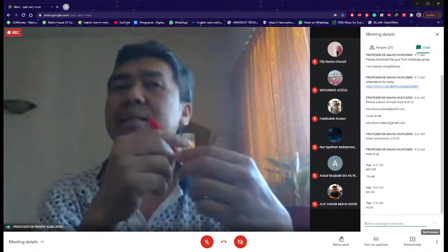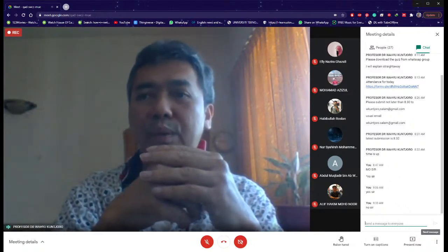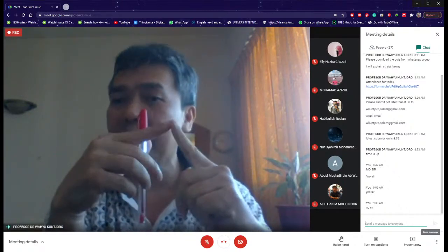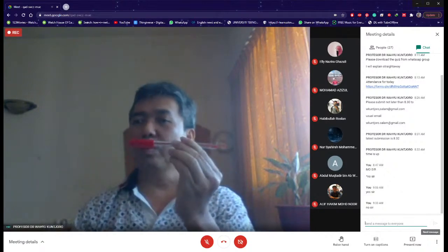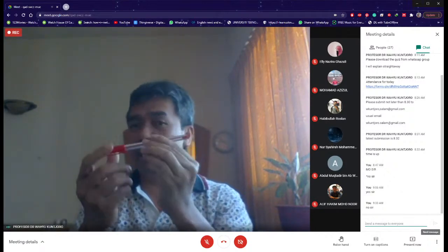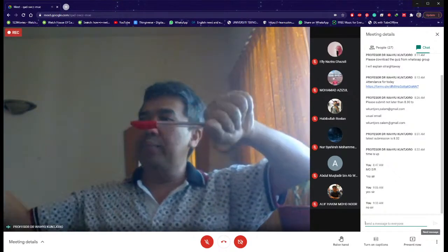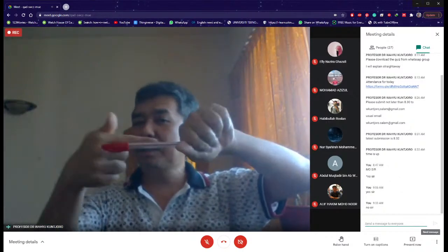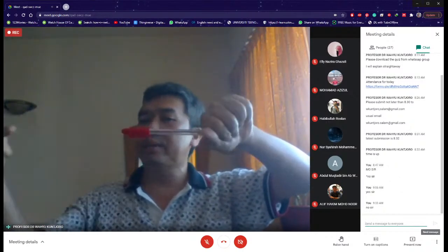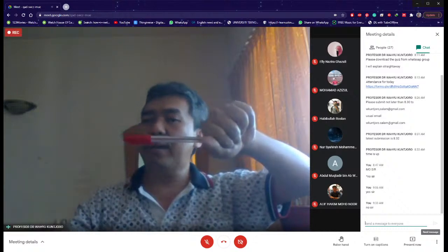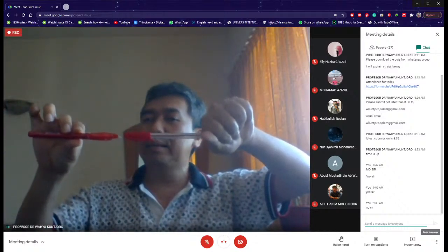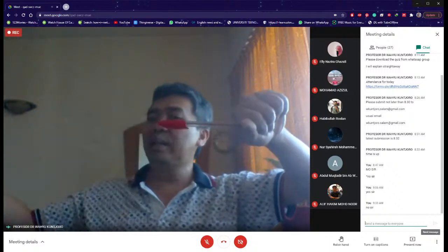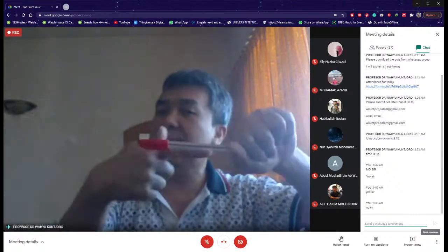In fact, we discussed before that truss is actually bar, but in two-dimensional. So bar like this, if I hold it like that, and I apply the force like that, it is bar. Definitely it is bar, because you have only axial behavior. So if I add another component and I connect this to that, and the loading is along that way, it is bar. Everything is axial.